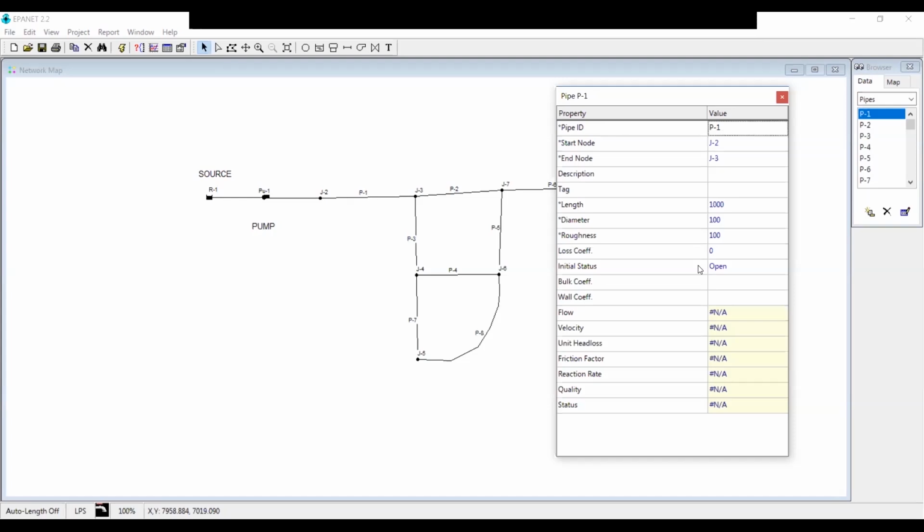All the things in the project should be consistent with real life. So that means, for example, you cannot use a pipe whose diameter is 100 meters. We will ask you, does such a pipe exist in real life, or for a pump? Because EPANET allows you to use anything. You can use any power pump in EPANET, but it should be consistent with real life.